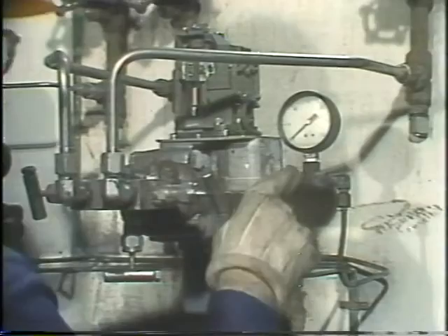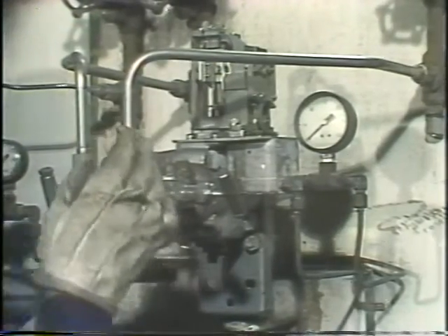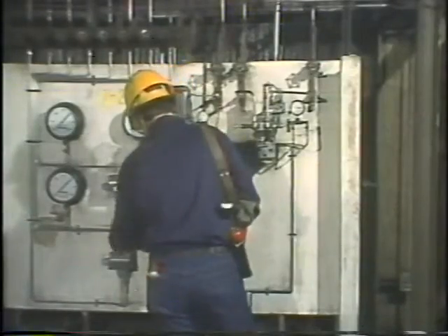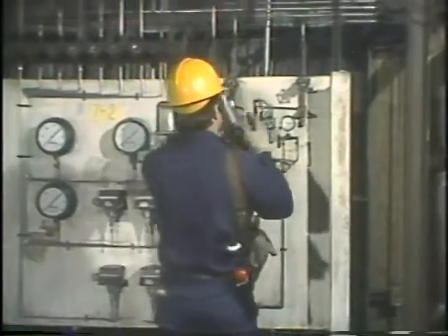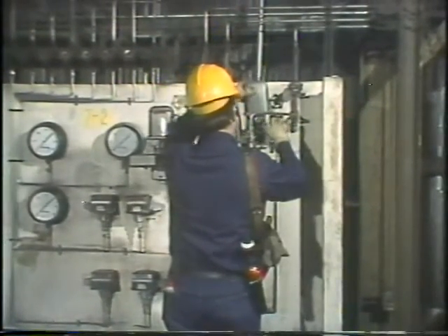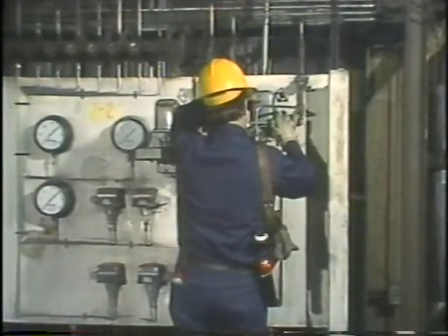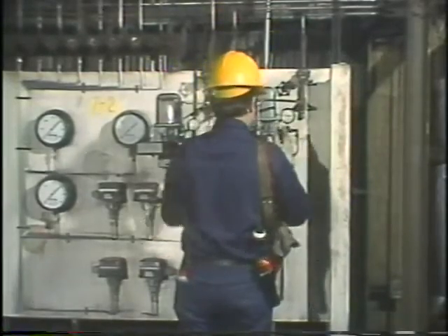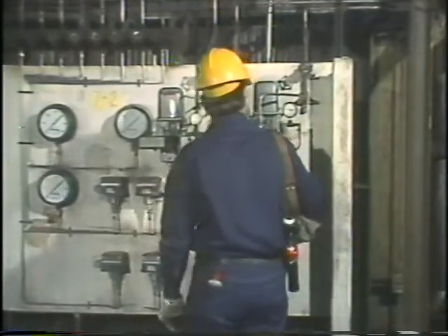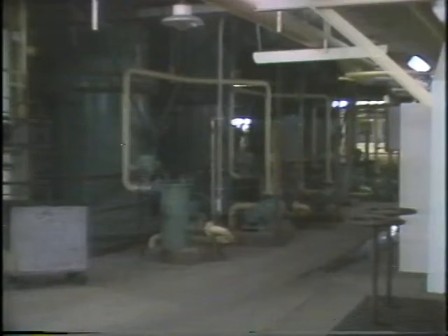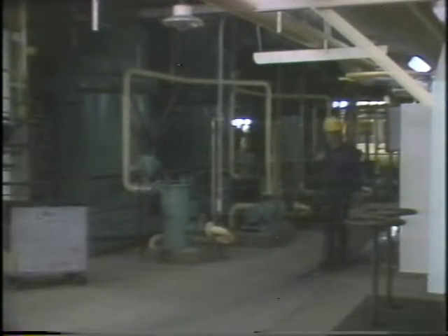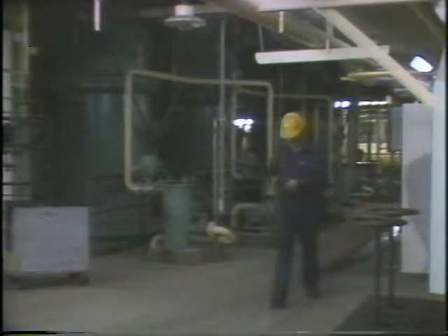Look at that, the output's 0. There is something wrong with this transmitter. So now the question is, is there a major problem, or is the transmitter just out of adjustment? To check it, I'll need a portable calibrator. That way, I can apply a known input value and check the transmitter's output. So now, Bob will have to go back to the shop to pick up the calibrator and the necessary tubing he needs to make the checks.